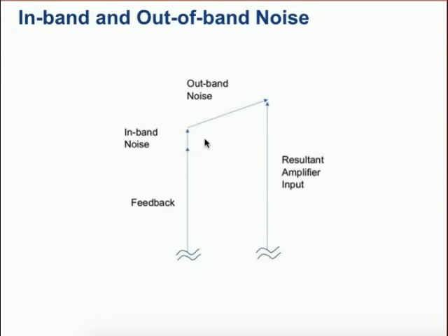Now at the other extreme, let's consider what happens to noise at very high offset frequencies. Noise at the noise floor of the oscillator. Now here we're so far away from the bandwidth of the feedback system that the feedback system doesn't follow at all the noise.